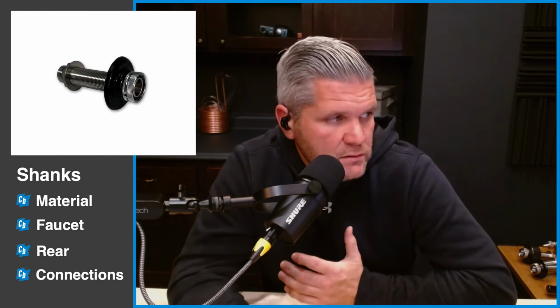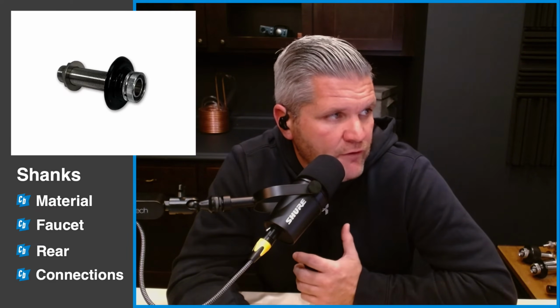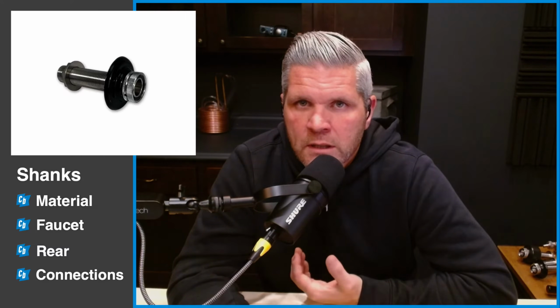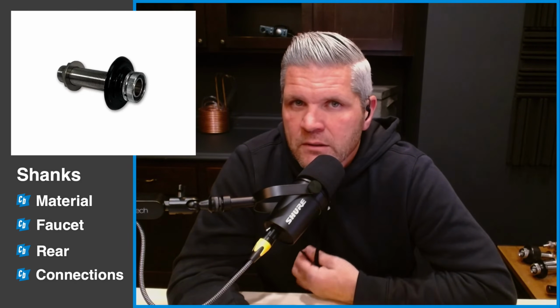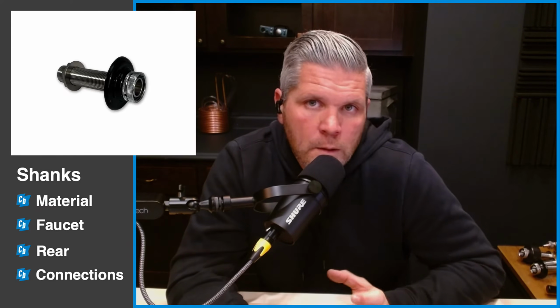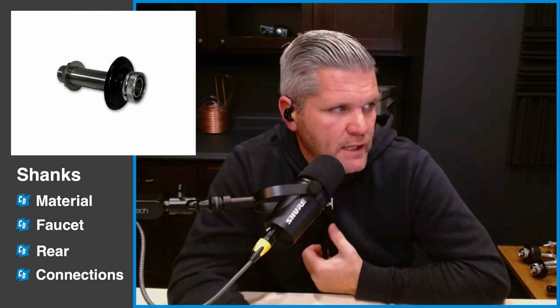Okay, moving on. From the tubing, the very last part is going to be faucets. But in order to connect our faucets to the tubing, we use what are called shanks, right? So beer shanks, there's 2 types. They're going to be a faucet shank, or we call them rear shanks here because that's just what they were in jockey boxes, but I think the technical name is coupling shanks. So you're most likely going to see a faucet shank.